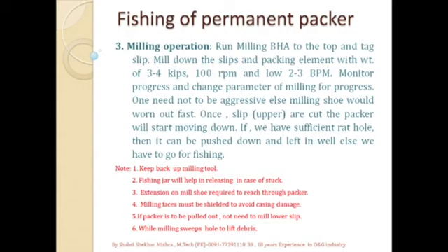Milling face of the shoe must be shielded to avoid the casing damage. If the packer is to be pulled out, no need to mill the lower slip.